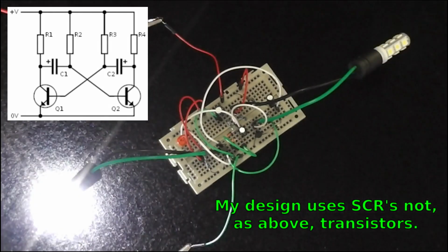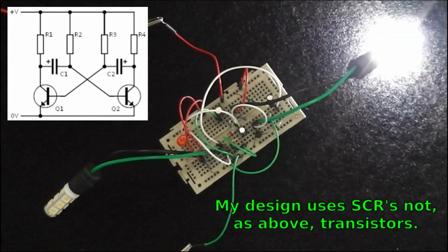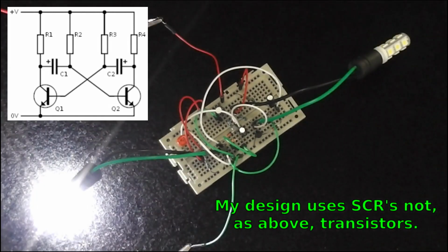I wanted a greater challenge than that, so I elected to use SCRs, and as you can see, the alternate flashing T10 LED car bulbs are driven using SCRs, and they are silicon controlled rectifiers. An SCR is fundamentally a diode that goes into forward conduction when the gate or trigger is applied. In AC conditions, which is where SCRs are mainly used, there is of course a reversing of supply, and that turns off an SCR. In a DC environment where there is a constant voltage, an SCR will stay conducting because there is no trigger or node to turn it off.